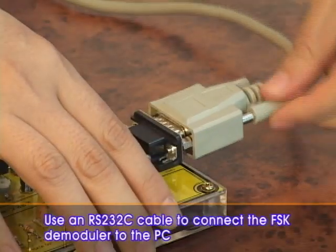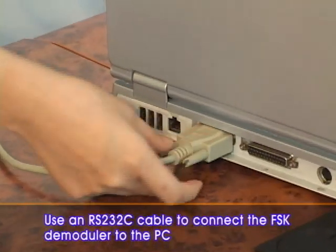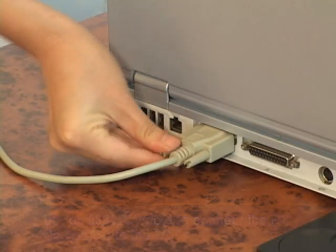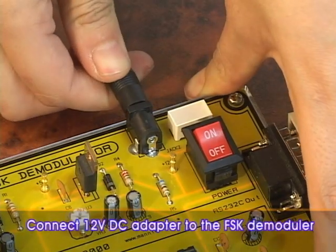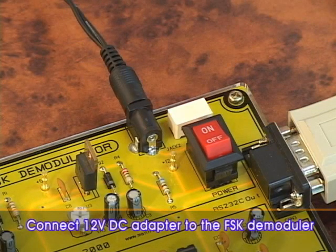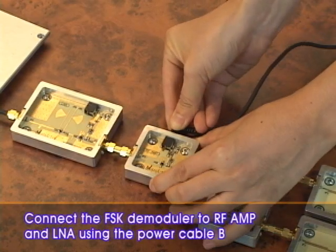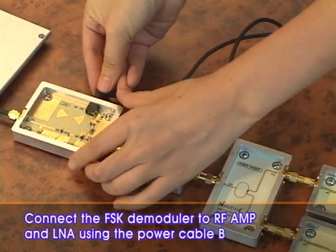Use an RS232C cable to connect the FSK Demodulator to the PC. Connect the FSK Demodulator to the RF amp and LNA using the power cable B. Connect the 12-volt DC adapter to the FSK Demodulator.